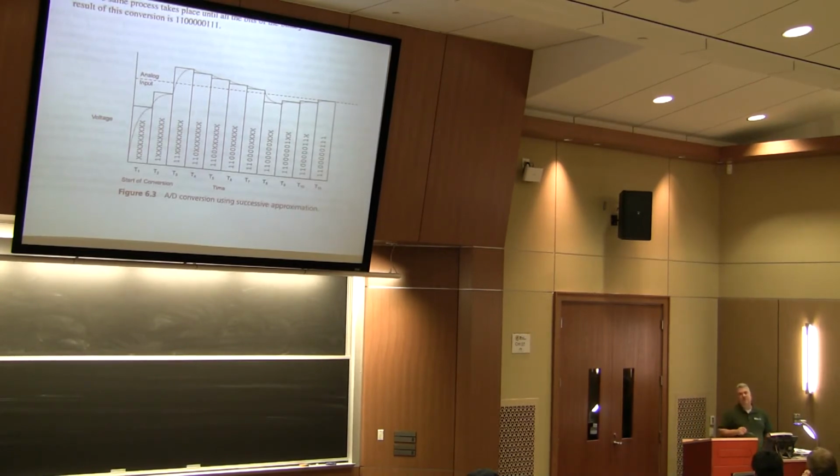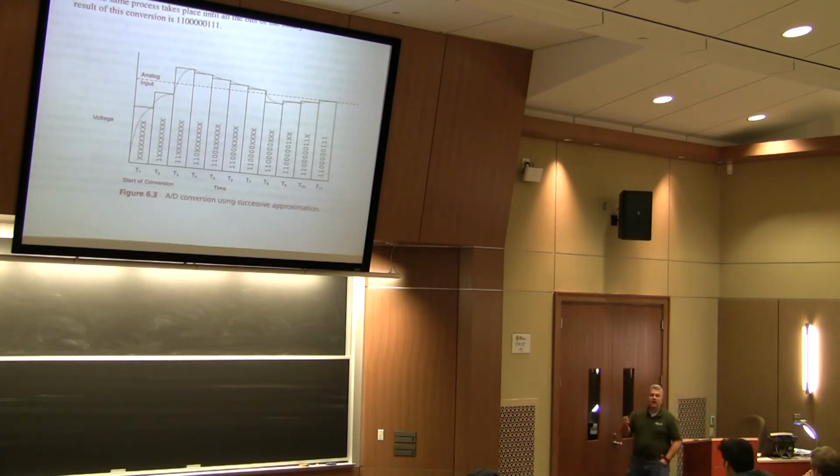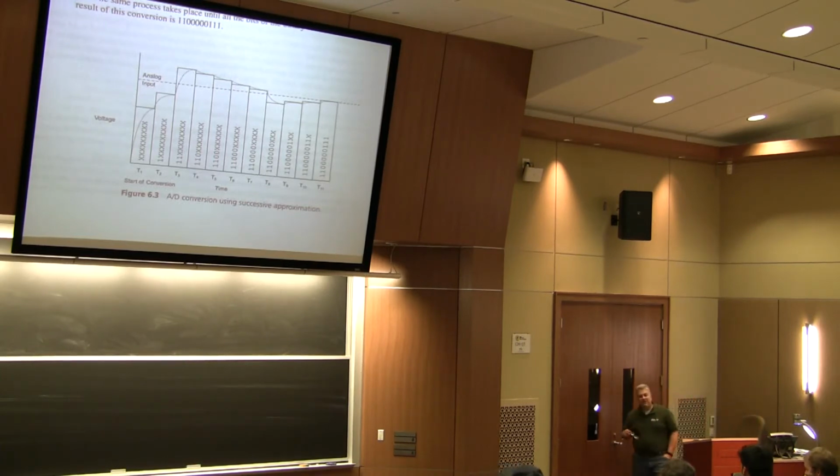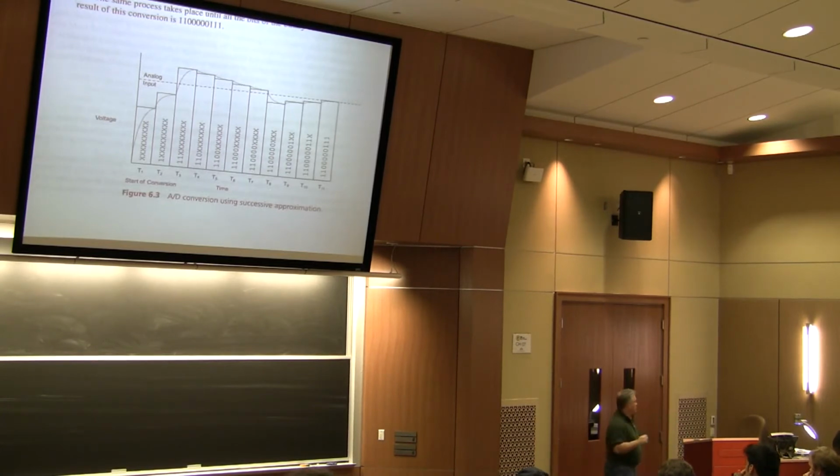One thing I could add on top of this is there are other ways you could do it. You could do it with a resistor ladder, in which, by having several resistors together with voltages as it goes through, you're making comparisons with comparators between two voltages, the input one and the one at that point. So this is just the way it does. It actually is one of the fastest ways to approximate your data. The number you see over there is representing something like a voltage. So let's look at what that voltage is.